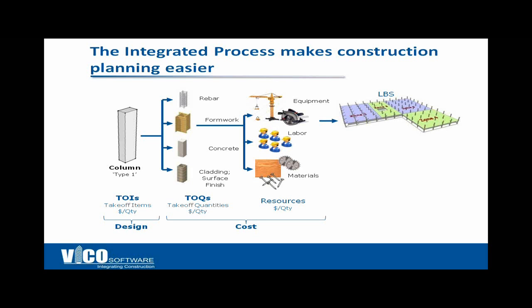In Vico, there's a huge thread on LinkedIn about how difficult it is to split the slabs in construction models. So I'd like everyone to be clear: Vico automatically splits these models up using its location management system that's part of Vico Office. It doesn't matter how many models you put together, and it doesn't matter how big or small they are. In Vico, we simply draw these lines in plan view to create these zones or location systems, and then we tell the system what we want to include in that location.